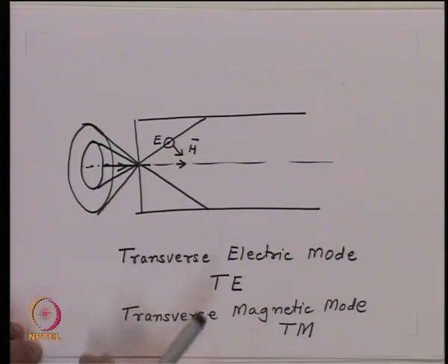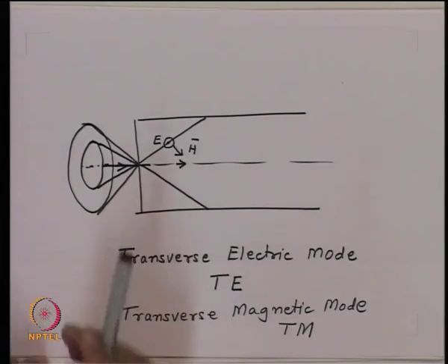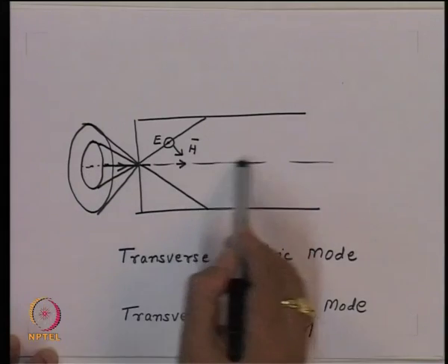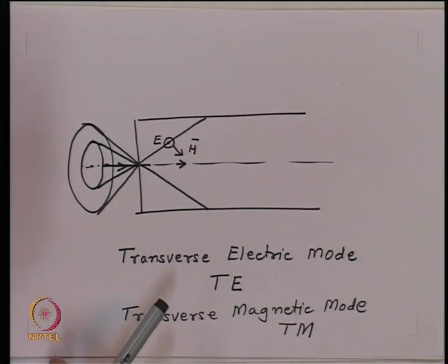So, from a dispersion point of view, the multi-mode optical fiber is a very bad fiber because it has a very large pulse broadening, and single mode optical fiber is the best optical fiber because it does not have any dispersion; only one ray goes inside the optical fiber. However, one would notice that if the diameter of the fiber is reduced to a substantially small value, then the numerical aperture cone also reduces in this process. Only one ray can be launched along the axis. So, the launching efficiency of this fiber is extremely small.